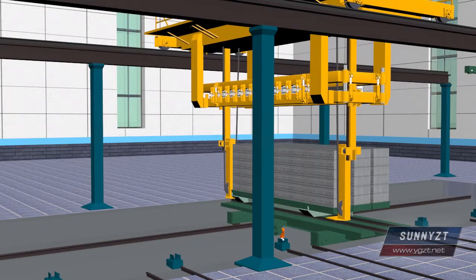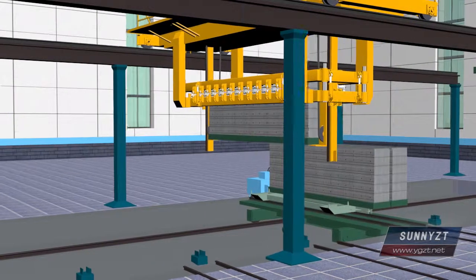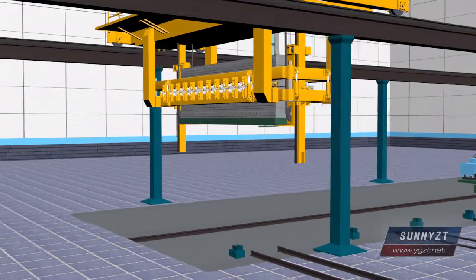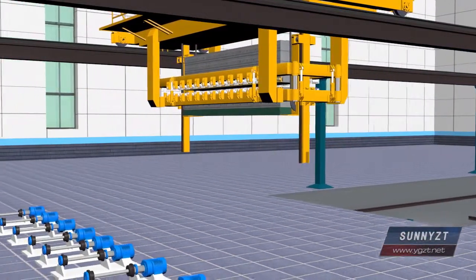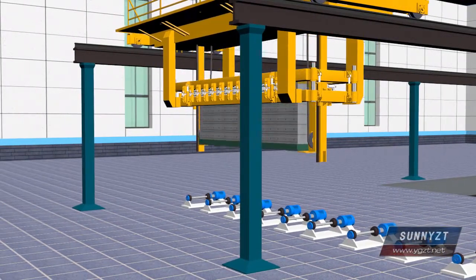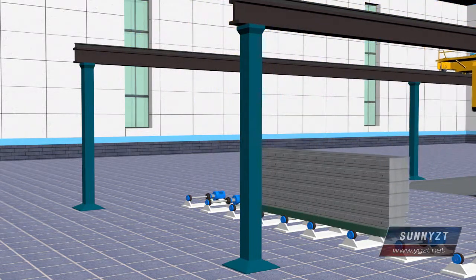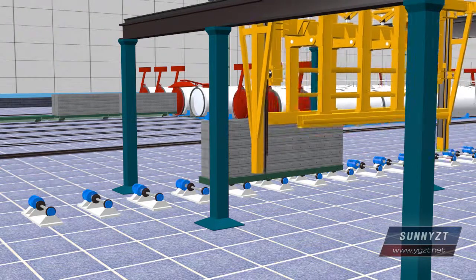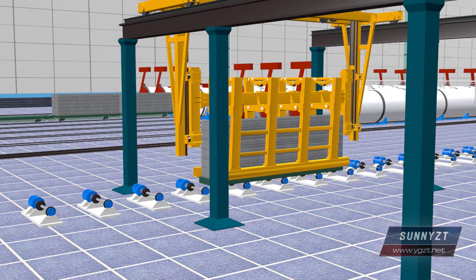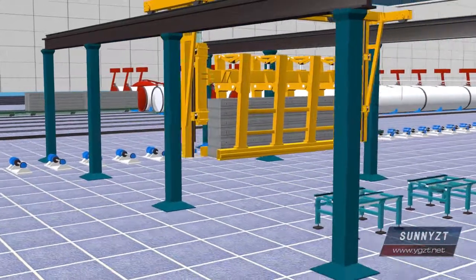Use the mobile severing machine to clamp the finished product and the side plate, then sever from top to bottom while moving. After severing, place the finished product and the side plate on the side plate conveyance line. Use the finished product crane to hoist all the finished products onto the finished product packaging conveyance line and convey them to the stockpile.